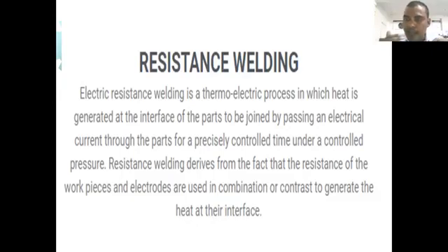The high ampere heats the joint, because heat is generated in resistance welding, and this heat generated is expressed by an equation known as H equal to I square RT. My dear student, this equation is very important to understand resistance welding. H equal to I square RT.